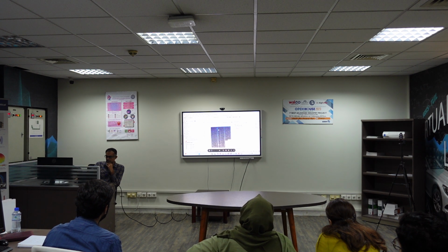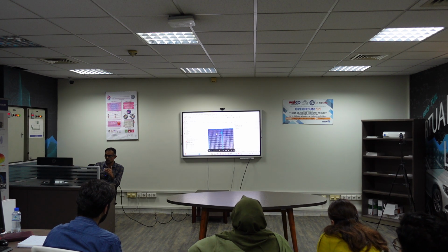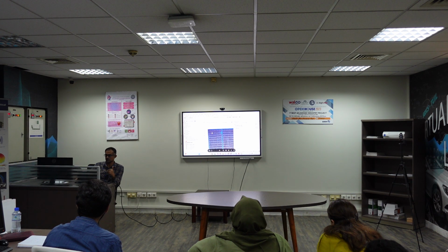You can see that I have the portion that does not comprise soil. I have put them in a validation mask. Then using that validation mask, I have derived the soil mask. Other than that would be the soil mask, obviously. And I have then sampled those soil mask points for height points, and using those height points, I have come up with this digital model